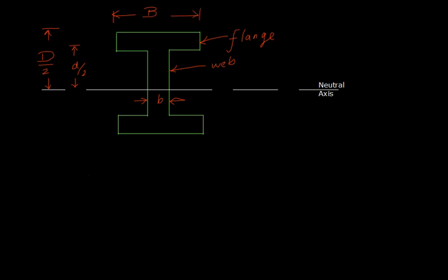Okay. Now, what is the layer that is under investigation? The layer that is under investigation is considered here, because I'm interested in finding the shear stress at this particular layer, and this layer is considered at a distance of y from the neutral axis.